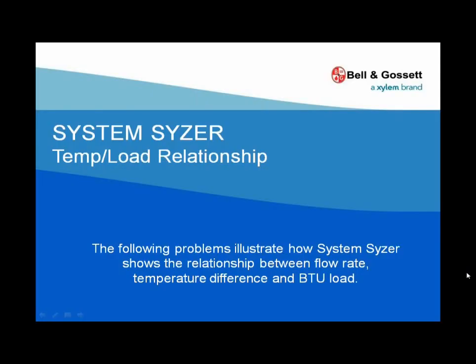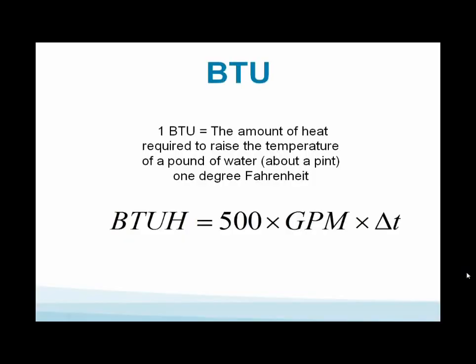We've got to start with what would be the old scale 1, and it's basically the temperature relationship between BTUs, delta T, and load. Just that simple. If you take a look at the old formula, I know everybody probably understands this, but a BTU is defined as the amount of energy required to raise 1 pound of water 1 degree Fahrenheit.